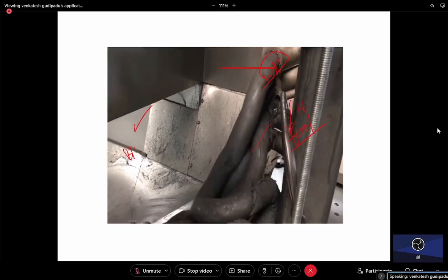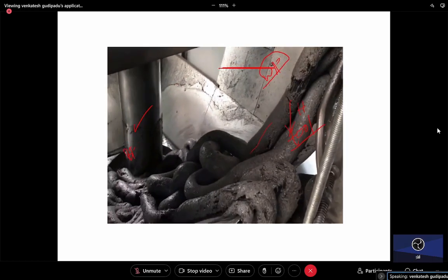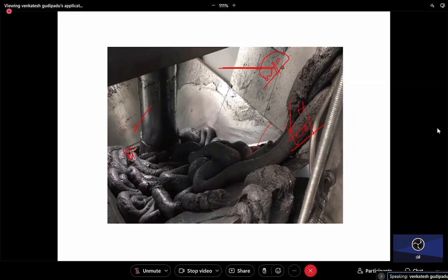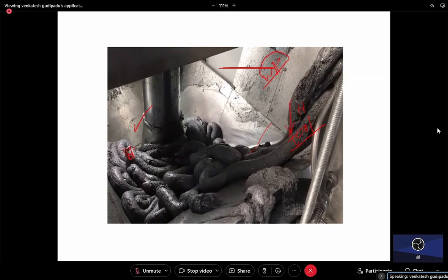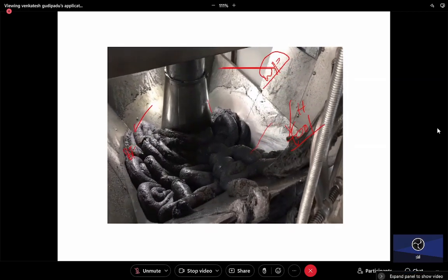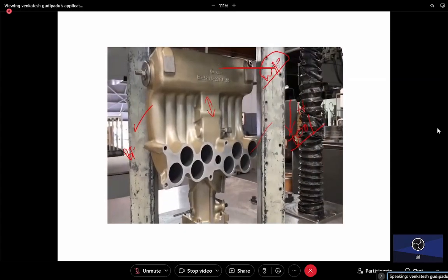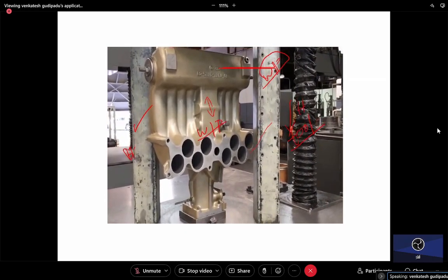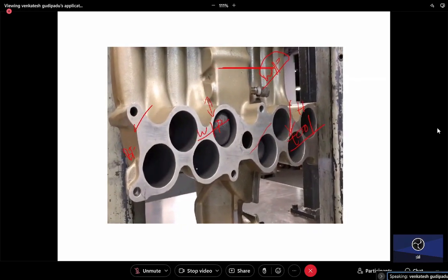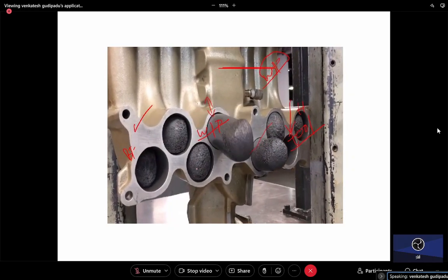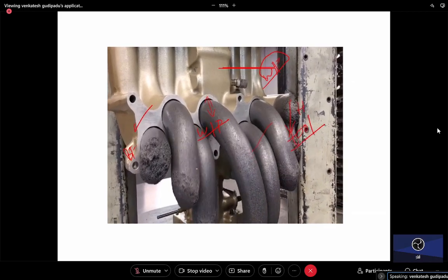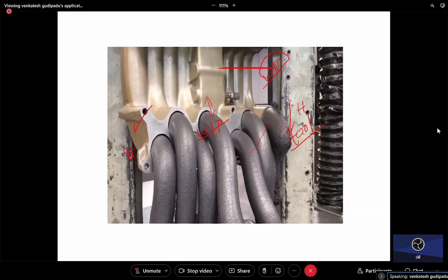Now you can understand how complex the workpiece is and how the intricate geometry can be finished by using this technique. Here the reused media is again pumped to and fro by using this hydraulic. We are pumping the medium through the target surface. My target is to finish the internal geometry of this workpiece, which is generally used in our car engines or automobile engines.